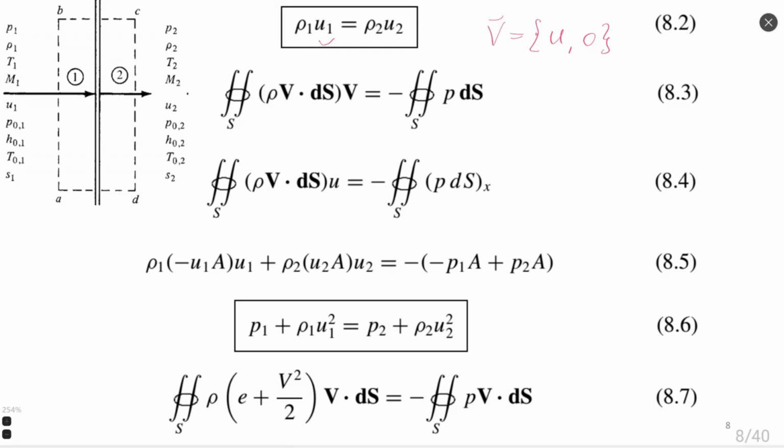It does not have body forces, just has pressure forces and the momentum flux over the surface, the left side of the equation. And further, it can be simplified when we assume that our velocity consists only of one component. Instead of the v velocity, we just use the u component of the velocity.